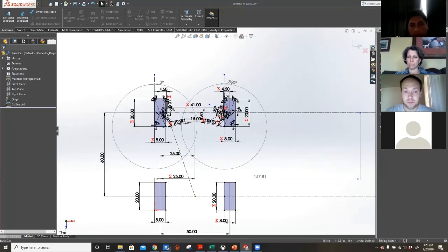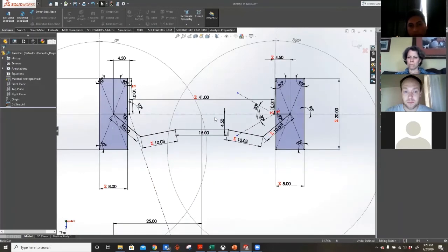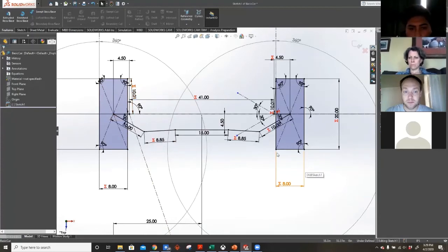And let's try moving your connecting point. Make the radius small. Make it connect still excess Ackerman, but put it closer to the steering axis. So maybe make it like 30 degrees and make the distance shorter. 30. 8. Go even shorter, go 7.